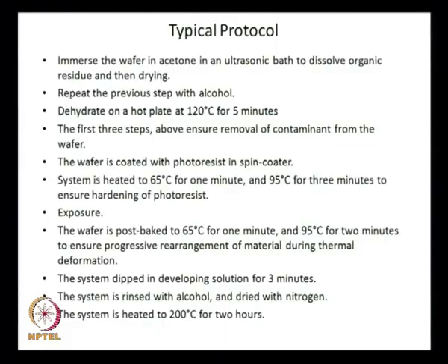So, you do not want that to happen, you want to wrap it up, freeze it and go to the next step. Okay. Next is the system dipped in developing solution for 3 minutes. What is this developing solution? Developing solution is that solution in which polymer is soluble, right. Many times it is potassium hydroxide, I think.